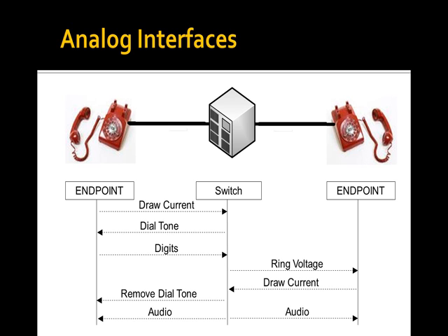They put a voltage across the line, they draw current, they do something to do this same sort of signaling. The ones you may hear about are E&M, ear and mouth, or earth and magnet, depending on which end of the argument where that term came from you want to. It's actually 2 control leads, one named E, one named M. Everybody made up names for them. And there are 8 variations on E&M signaling. There is something called ground start signaling, which was actually designed as a trunk. Loop signaling was not designed as a trunk. It was designed for a line. But it's cheap. So we use it. So anyway, we're going to limit our discussion to analog loop start.